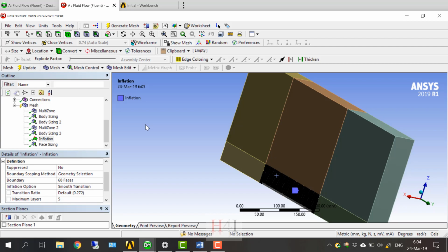The problem is when it occurs in a critical part and in a very large number. You can see this when trying to solve, as the solution will diverge. In Fluent, you can check the location of the divergence. If you find that the divergence occurs in a specific region, you recheck the mesh. If you find the mesh is skewed in this region, has a very high aspect ratio or very large angles, then the reason is that this mesh is not good. That's what I wanted to answer.